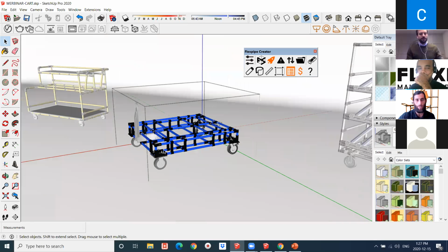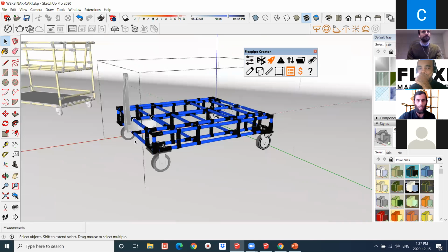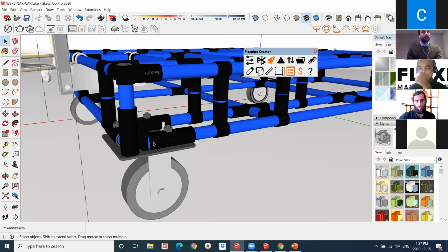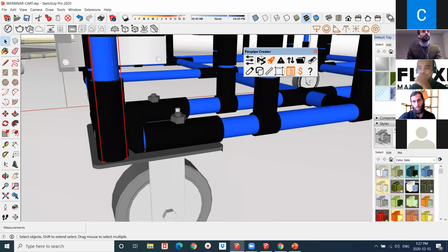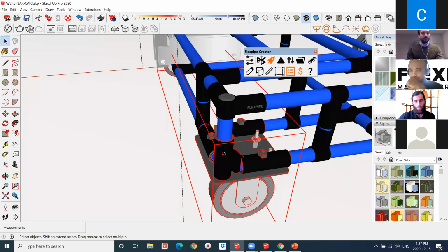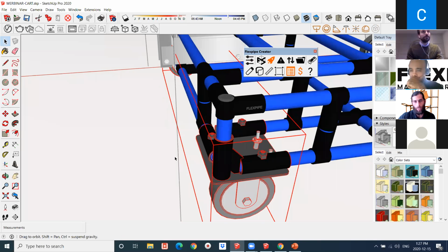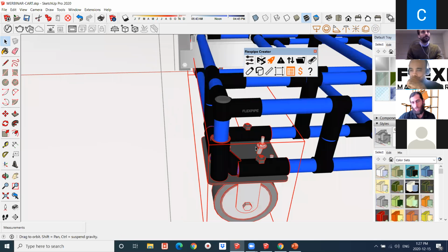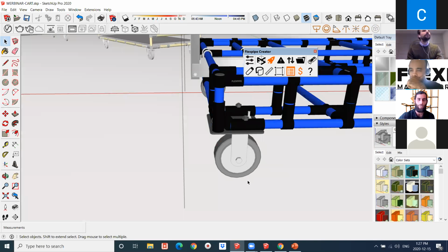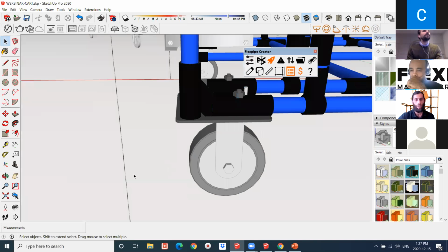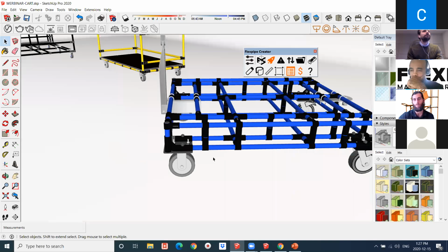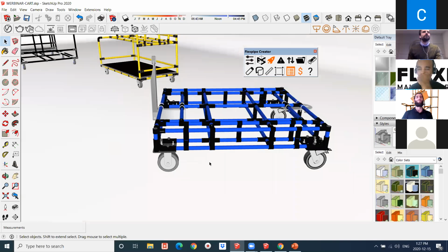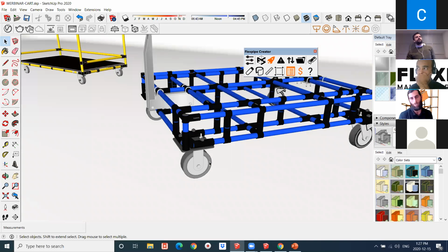You can see here that we're using the heavy-duty caster plates. So these are really going to hold this all together. They're joining the entire structure. We have a pipe on the vertical as well as 3 horizontals that are being joined together to this nice, strong, heavy-duty plate. And then we're using the 6-inch caster here to be able to transport easily without having any issue whatsoever when transporting. This is the kind of thing that we mentioned, right? If you're looking for a long distance transport, if you're having uneven floors, then do consider using the 6-inch caster.